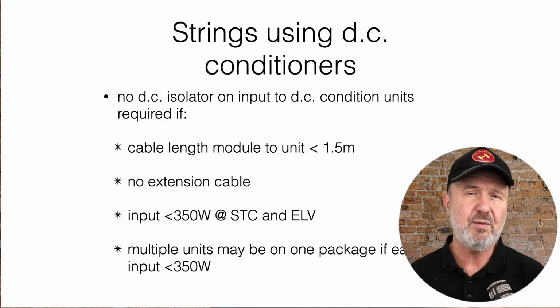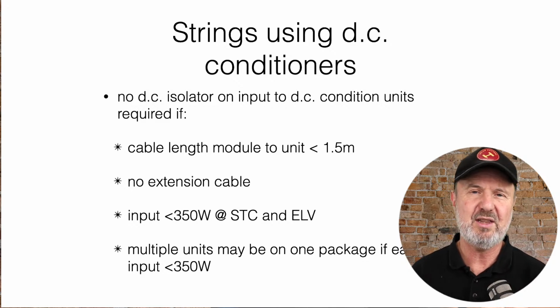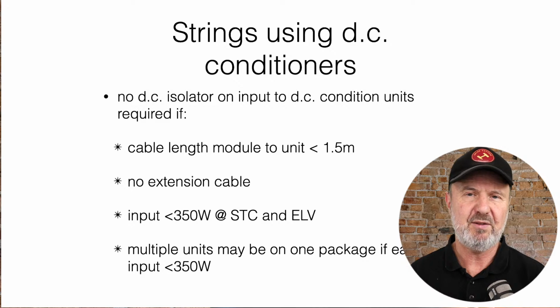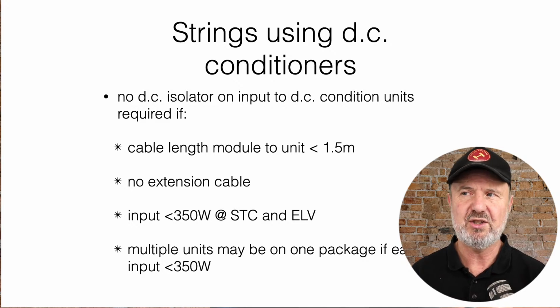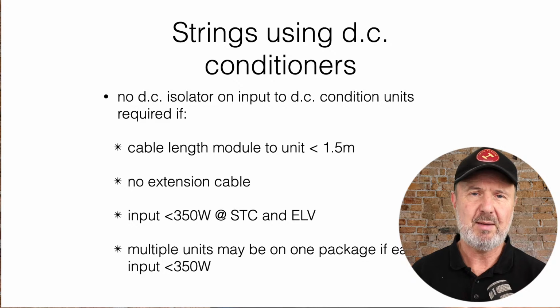Many of them kind of work together. You sort of plug them in and you think they're the same thing, but they're not manufactured to be pushed together. And therefore, we require that all plugs and sockets are the same brand, same type, both sides of the connection. But you are allowed to use adapter cables to overcome that, where your DCU, your optimizer, has brand X plugs and sockets on it, and your inverter has brand Y, and you can get a short adapter.